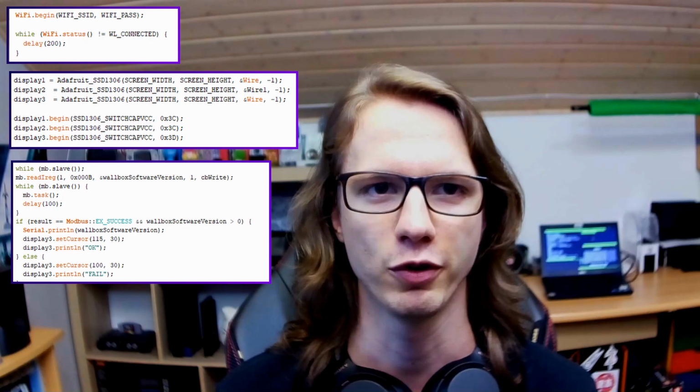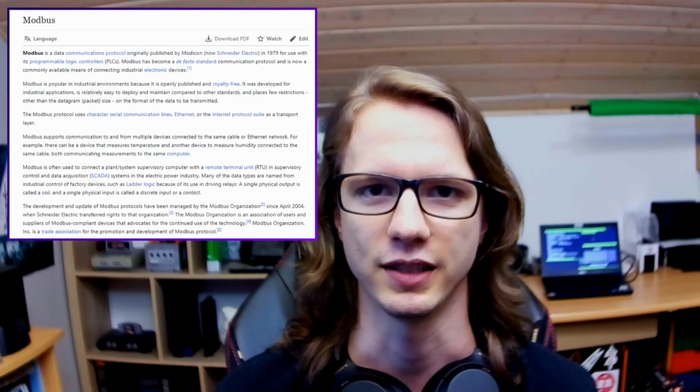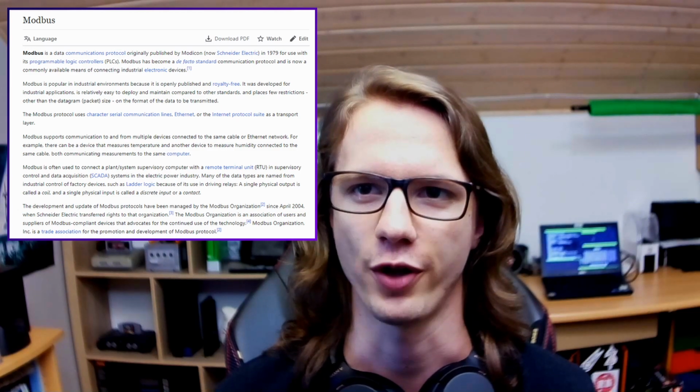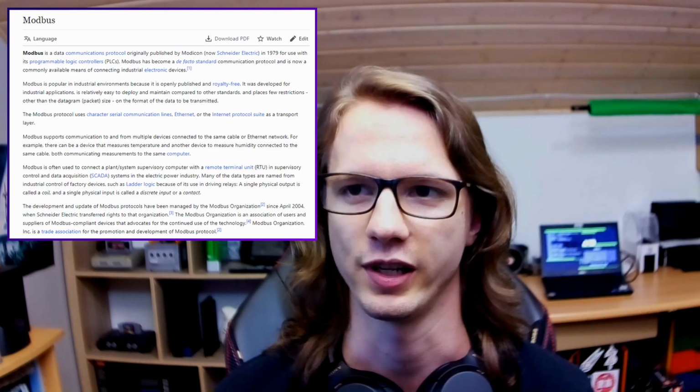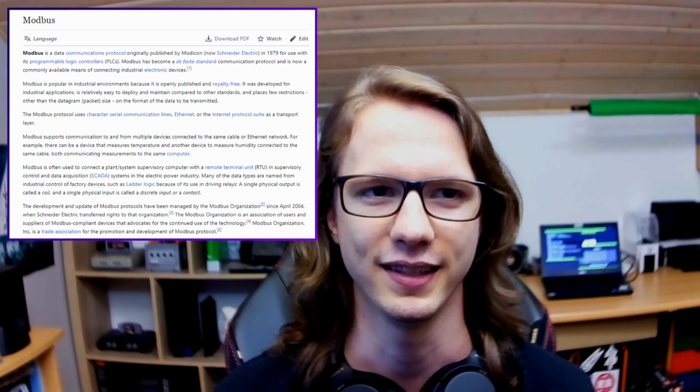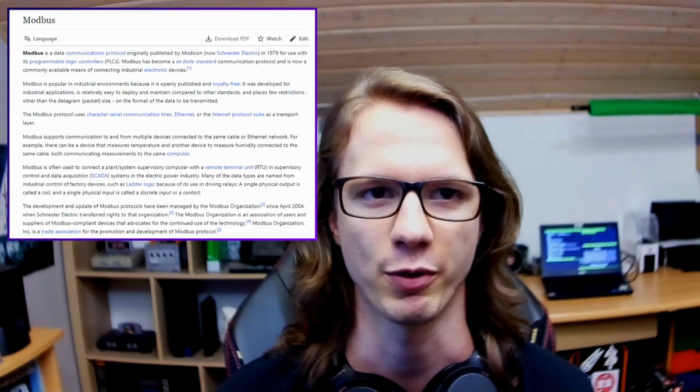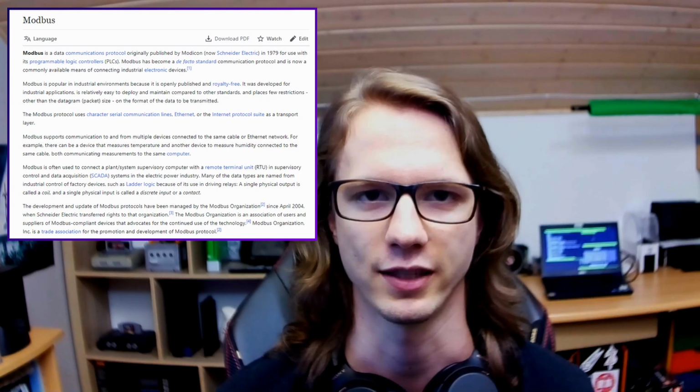Now that you know the most important limitations I had to work with, let me talk you through how it's implemented. Of course, everything starts with initializing Wi-Fi, the displays and the Modbus communication with the wall box. For those of you that don't know, Modbus is one of many de facto standards for connecting industrial devices. In this instance, it uses RS485 serial as a transport layer.